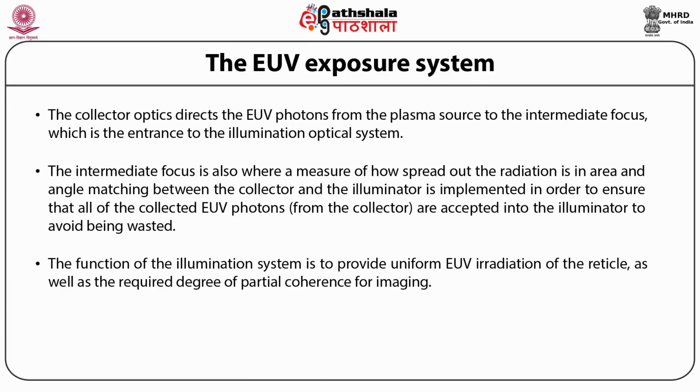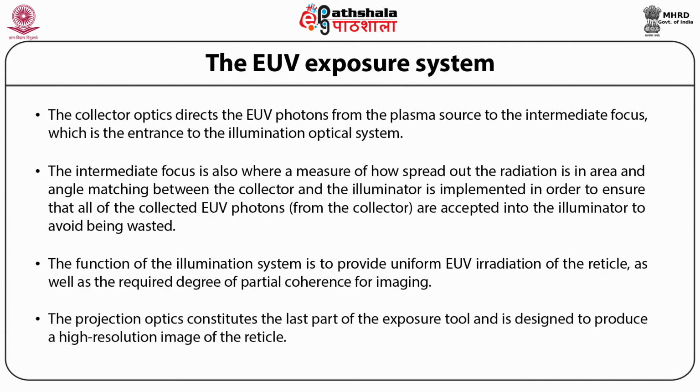Now the function of the illumination system is to provide uniform EUV irradiation of the reticle as well as the required degree of partial coherence for imaging. So the projection optics constitutes the last part of the exposure tool and is designed to produce a high resolution image of the reticle. It should also have very low distortion and aberration levels.